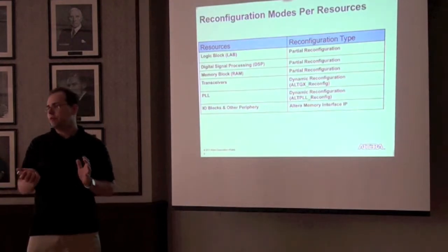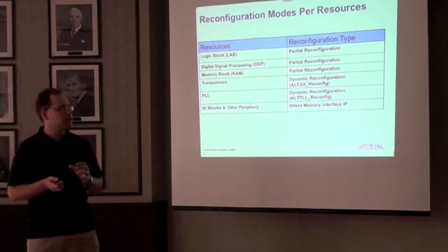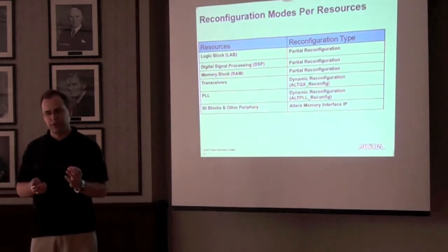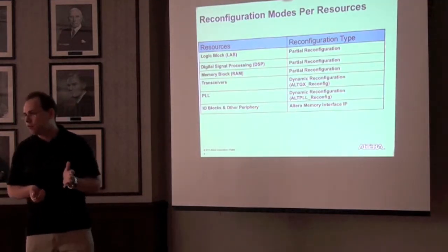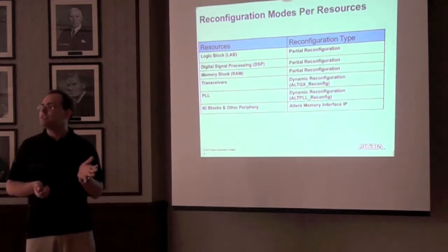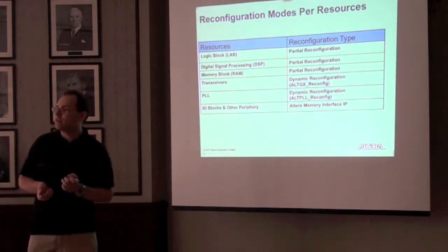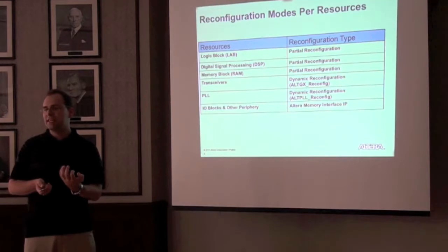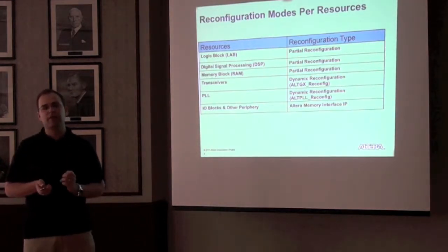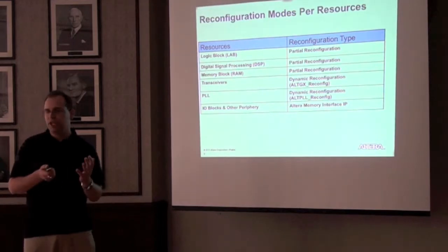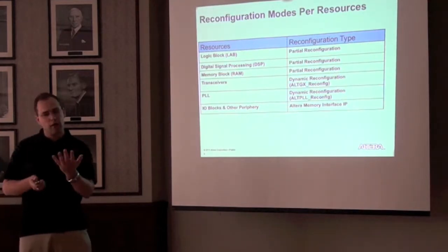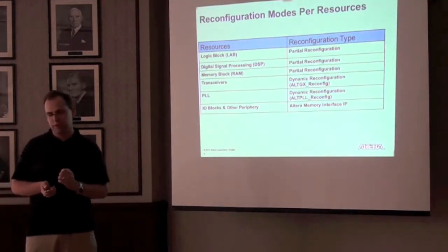So pretty much everything can be reconfigured, but not all of the hardware components can be reconfigured in the same way. The components in the core of the chip, that is the logic blocks, the DSP blocks, and the embedded memories, or the RAMs, are controllable by partial reconfiguration. Pretty much everything on the periphery is not. However, Altera provides IP for the transceivers and the PLLs that the user can instantiate in their design that allows dynamic reconfiguration of those capabilities. Maybe changing the latency of something, or changing the frequency of a PLL, and going into switchover mode. All of that kind of stuff is supported, but is not supported through partial reconfiguration.